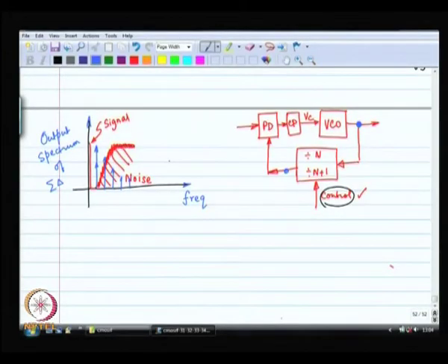So, that is what I have successfully broken, if I can claim that the control signal is coming from a delta sigma output which is no longer periodic. So, given that the control signal output is no longer periodic, you can expect the signal over here to be not periodic at 1 megahertz anymore, but yet you are going to do some sort of a division by n plus a fraction, okay, which means that you have done your job.